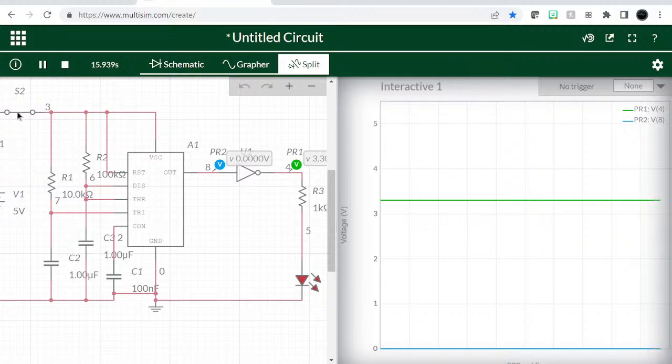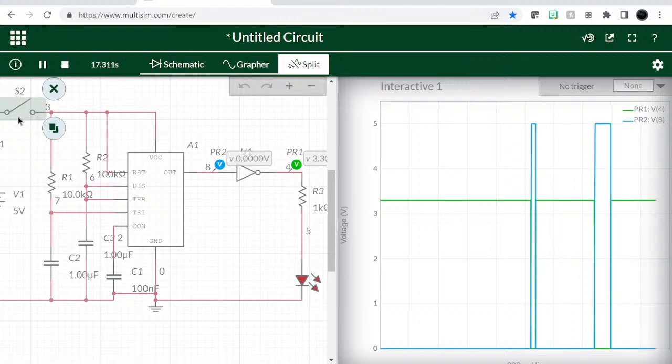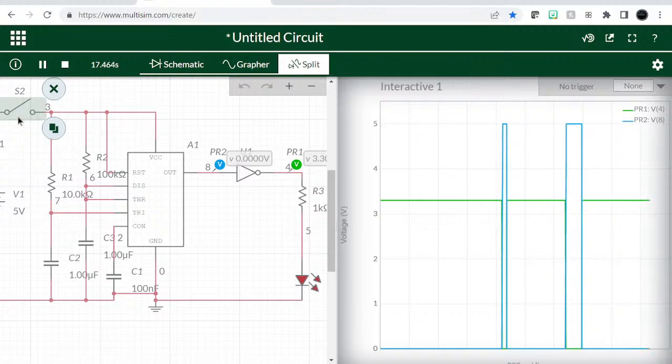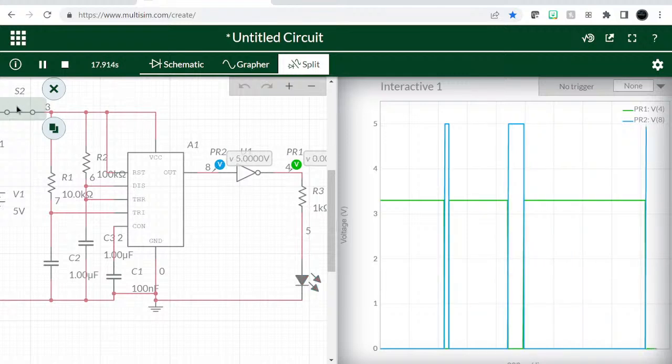Now, when I turn it on, the moment I turn it on, power goes in, and momentarily you can see there's 5 volts that shows up at the output. Let me see if you can notice that. Let me turn it off. When I turn it on, just notice right around here, it's going to go 5 volts and then it will drop. 5 volts and then drops.